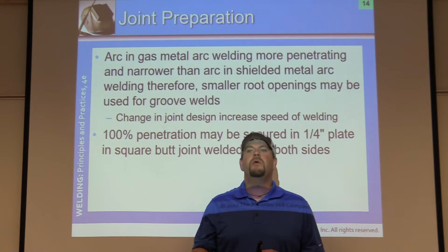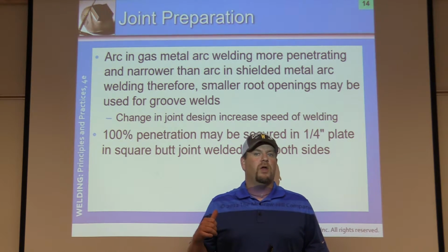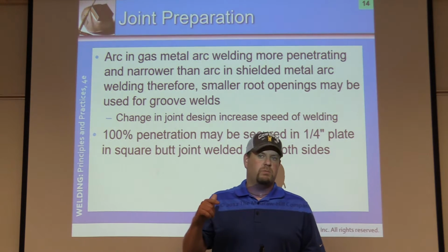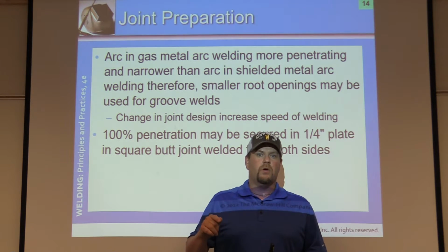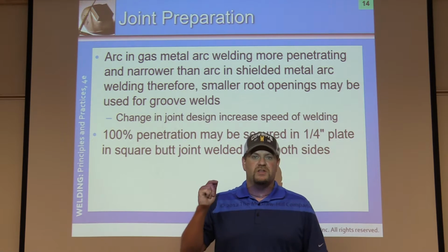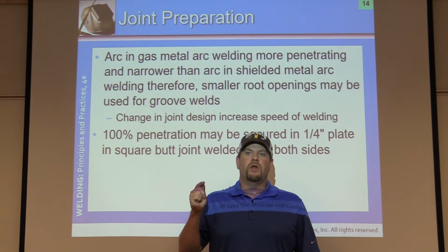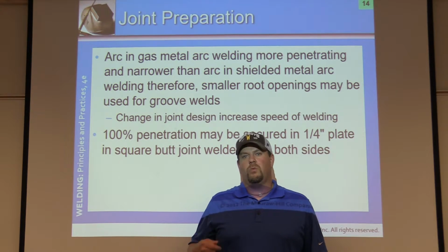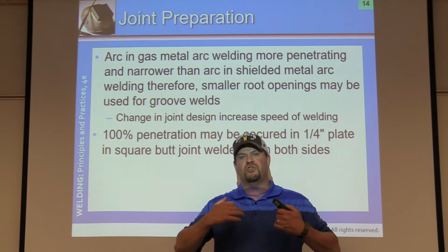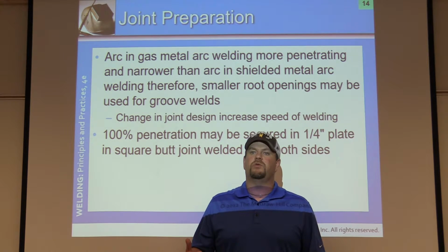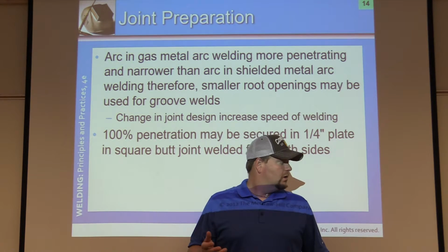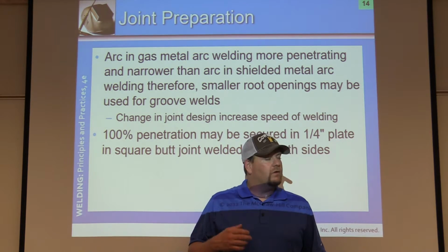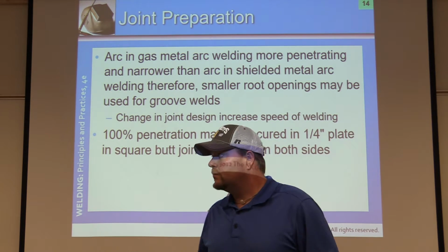Okay, so if it takes you 3 passes to weld a 1/4 inch plate, I would rather see that, and most manufacturers, company owners, and your employers are going to say the exact same thing. A good weld is much better if it takes you an extra minute than doing it all in one pass, running super hot, it distorts, it warps, and then you have a huge problem. Cut it back apart and start all over again, okay? All right.